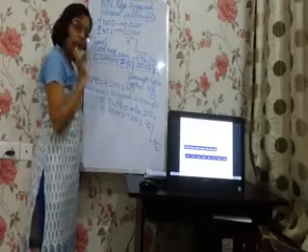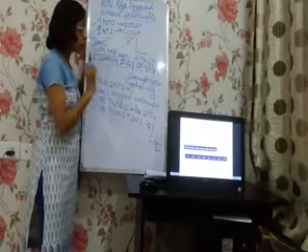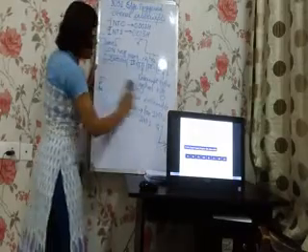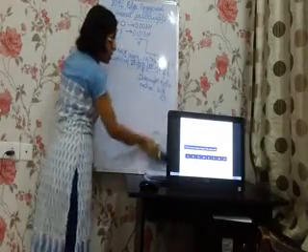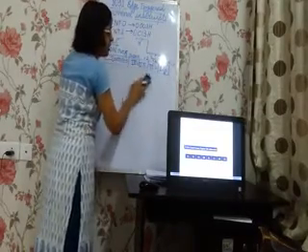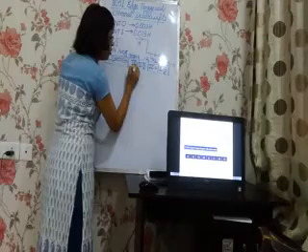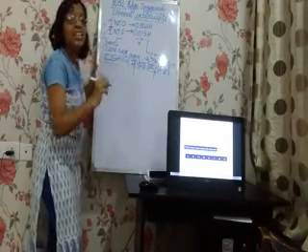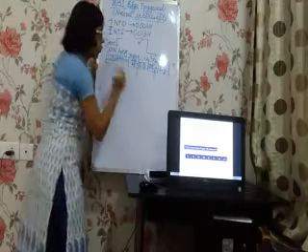I hope you have understood IT1 and IT0. Now what are these bits, IE1 and IE0? Let me talk about IE1 and IE0 bits now. We have discussed IT1, IT0. Now IE1, IE0. These are called interrupt edge flag control bits.